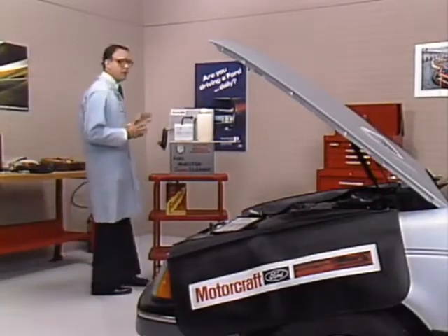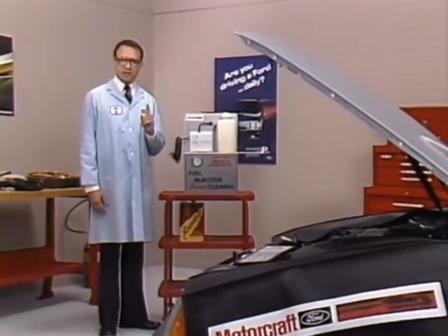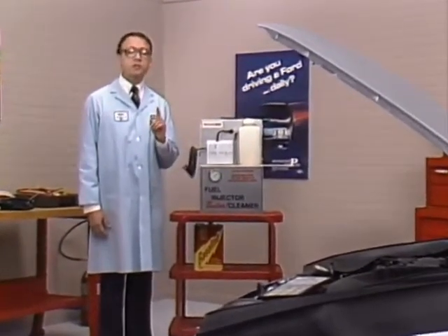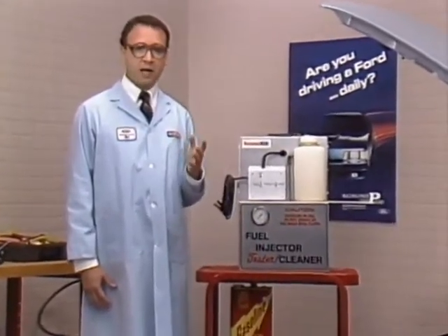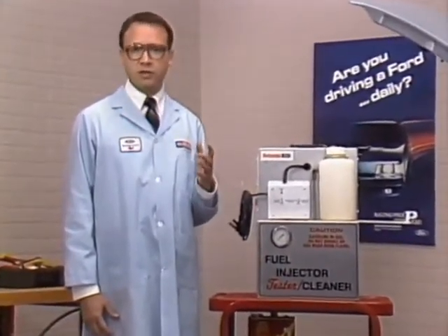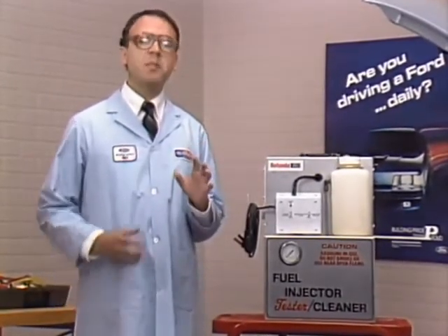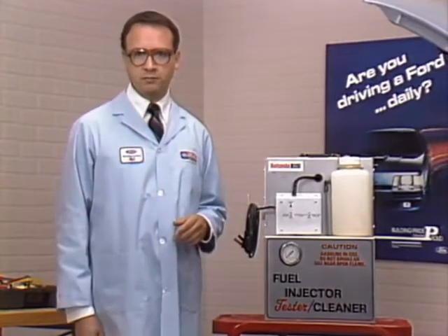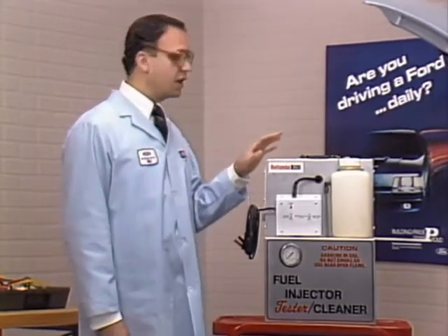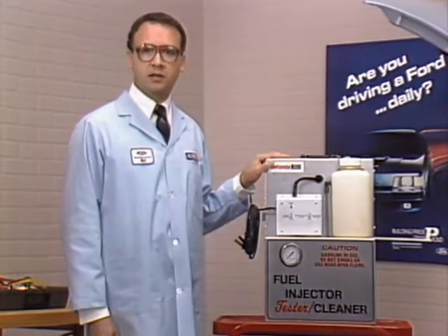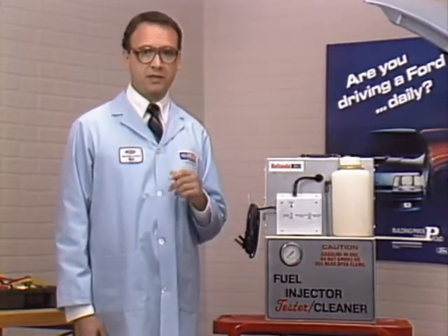Now, in some cases, your fuel injection system diagnosis may lead you to suspect that there's something wrong with the injectors themselves. For example, if the vehicle has a symptom like missing or lack of power, and you know that the owner's been using dirty fuel, you'd have good reason to think that one or more of the injectors may be clogged with dirt from the fuel. To find out more about the condition of the injectors, you can use the Rotunda fuel injector tester cleaner to both test the injector's operation and clean the injectors if necessary.